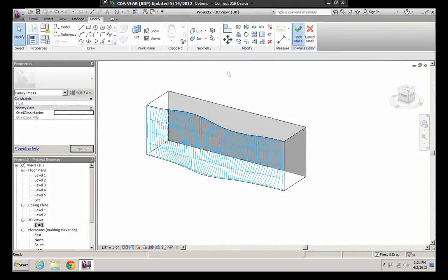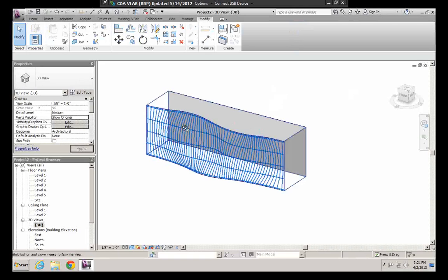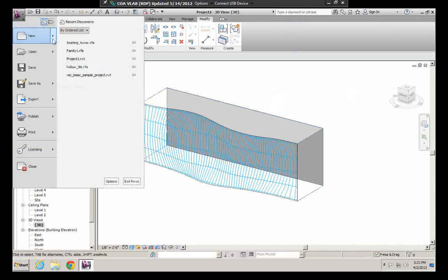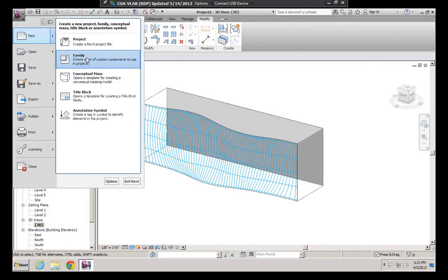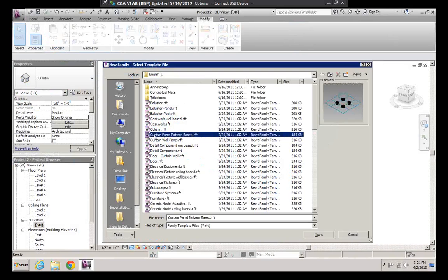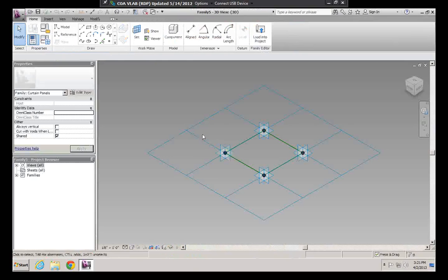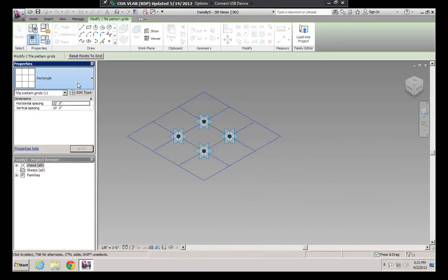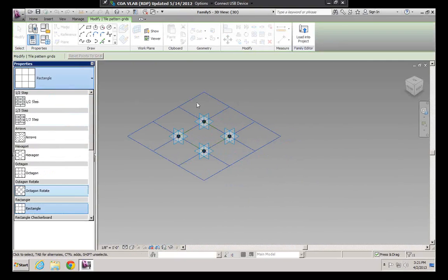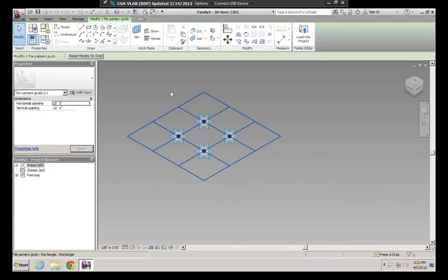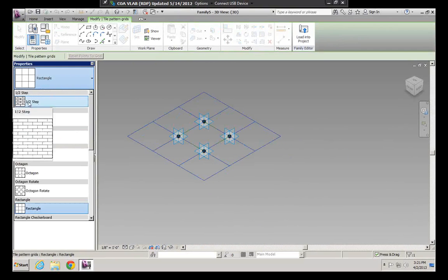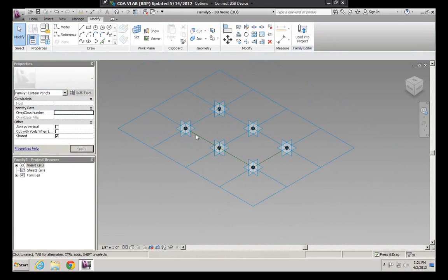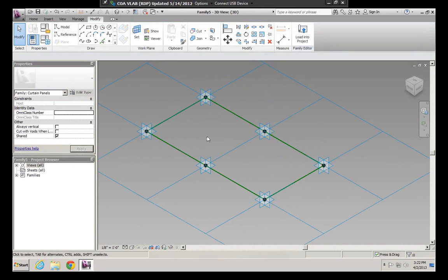And let's say we want to work with this. Now I finished the mass, and I want to create a new component here. So I'll go to Revit, New, Family, and I'm going to select Curtain Panel Pattern Based again. And for this one I'm going to work with a 1-2 family. So if you go to the properties on the top, I've selected the blue line, and I select 1-2 step, and this will create 6 adaptive points. And what I want to do is a folded surface here with some profile.